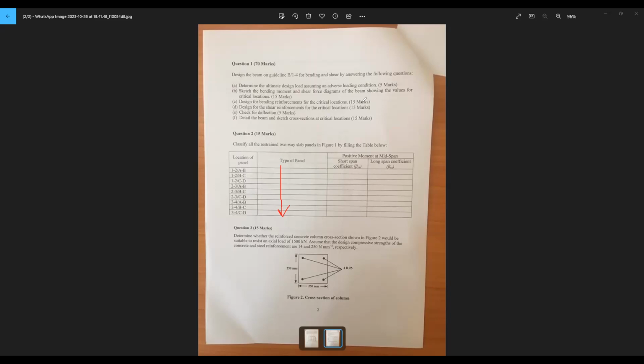We have classified them. Then the next step is to go to the other columns. We have some 3 rows there. On the first row, you have short span coefficient, BSX. And under that, you have values of Ly over Lx: 1.0, 1.1, 1.2, 1.3, 1.4, 1.5, 1.75, 2.0.